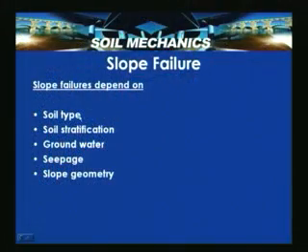So, slope failures depend on soil type, soil stratification, groundwater, seepage, and slope geometry. These things are very important. Slope geometry means the steepness of a particular slope. So, soil type, soil stratification, groundwater, seepage, and slope geometry.